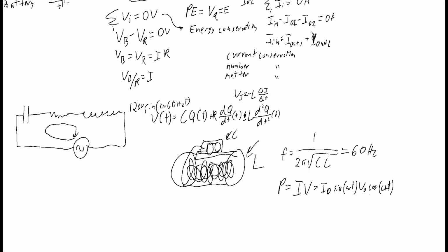Can it go all the way? Yes, so you get 90 degrees out of phase, and so this will actually minimize the amount of power you can deliver. By realigning with the capacitor, instead of being here with the sine, it comes in with the cosine. Now that they're aligned, you get the maximum power out. And so you're not fighting the current, the power in the line, to do your work.